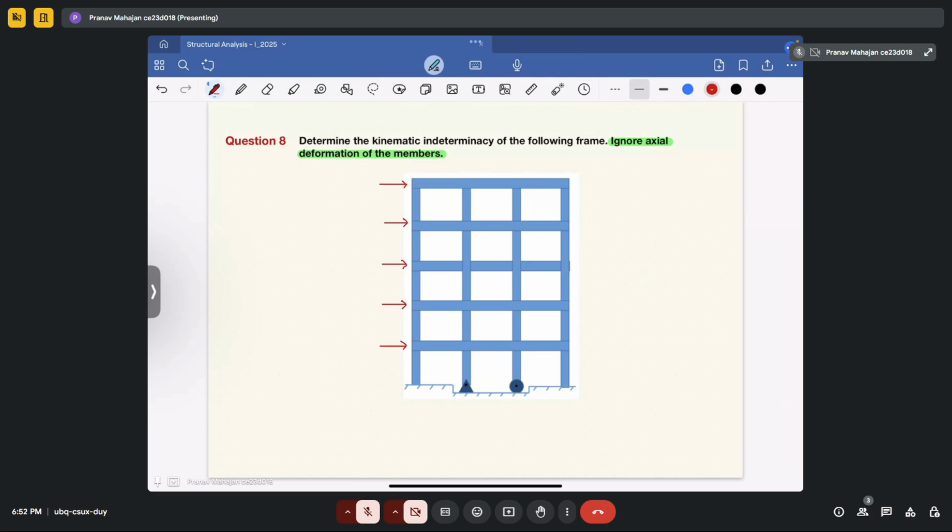So that means if you are applying horizontal force in that whole structure, you will observe rotations also in the members. So these rotations are not equal in each and every bay frame. Okay, so that means your rotations at each and every point will be unknown, and you have to determine the moment at each and every point of the section. So all the elements of these bay frame will observe unknown reactions due to the moment.